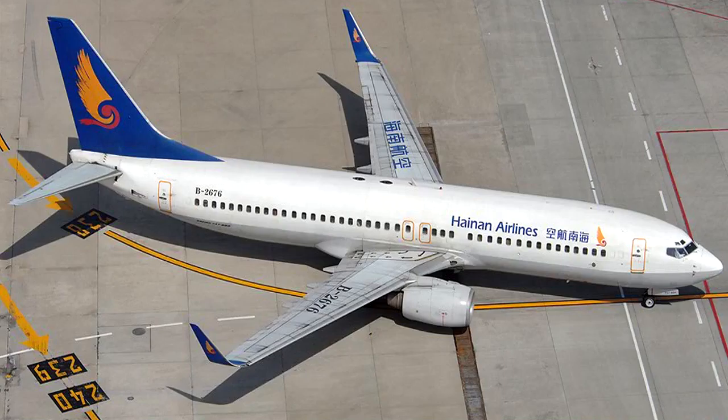With the increased size of modern airports, taxi distances have also increased, thus increasing the amount of tyre wear and risk of damage. To minimise tyre wear, it is recommended that a speed of no more than 25 miles or 40 km per hour should be reached during the taxi run.